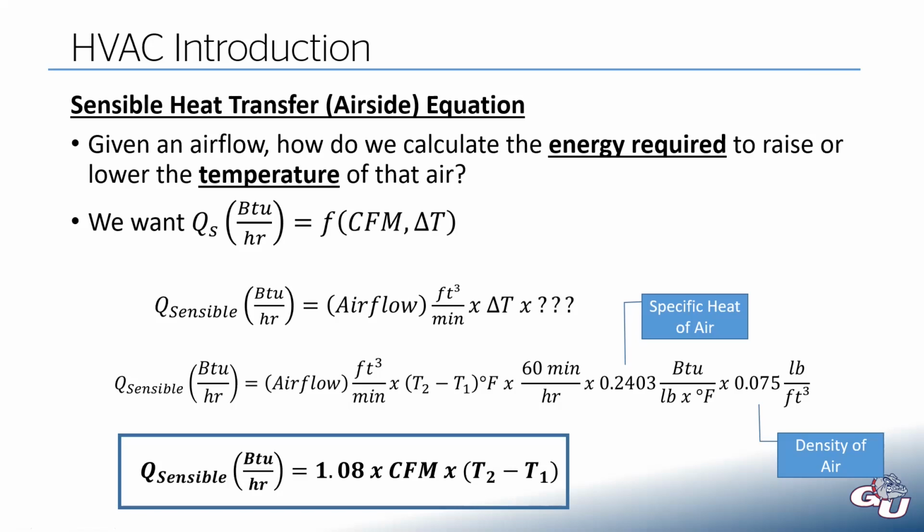So our sensible heat transfer is entirely based on how much air we are moving and what the temperature change of that air is. It's not based on the water content whatsoever. And if you think back to the last lecture, the pre-recorded one, when we were talking about infiltration, this is the equation I just gave you at the time and said, trust me, this is it. But this is where it comes from.